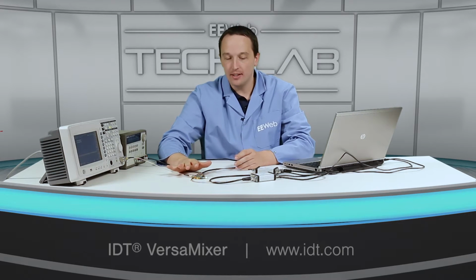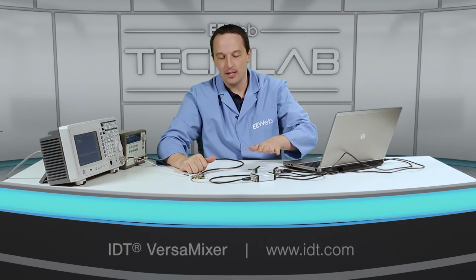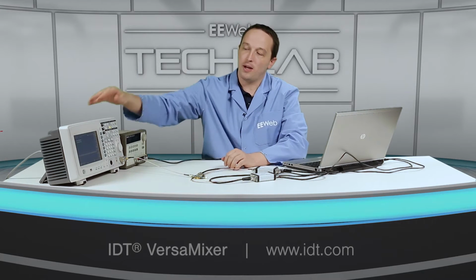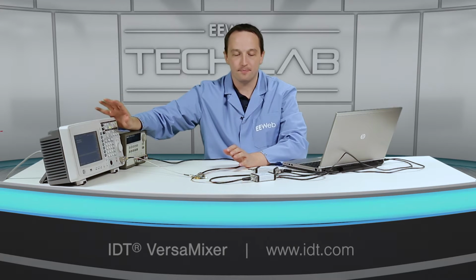All right, so with everything connected, I have my two synthesizers. This is connected to the RF input, this is connected to the LO input. I'll set the RF to 1000 megahertz and the LO to 800 megahertz. I've got my spectrum analyzer set to a center frequency of 200 megahertz to capture the IF output.